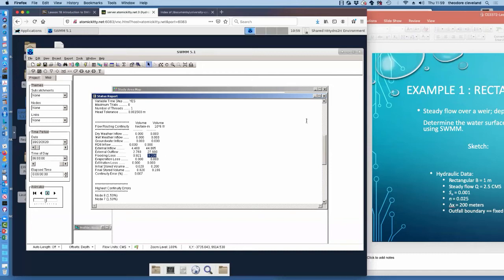So that number itself is actually meaningless, but when you see a non-zero flooding loss in the report, and you're expecting to contain everything in your drainage network, the program has given you evidence that your design is insufficient. And then you would use that profile plot like I was showing you to attempt to locate where that's occurring and then make necessary design corrections, rerun the hydraulics, and we're all happy campers.